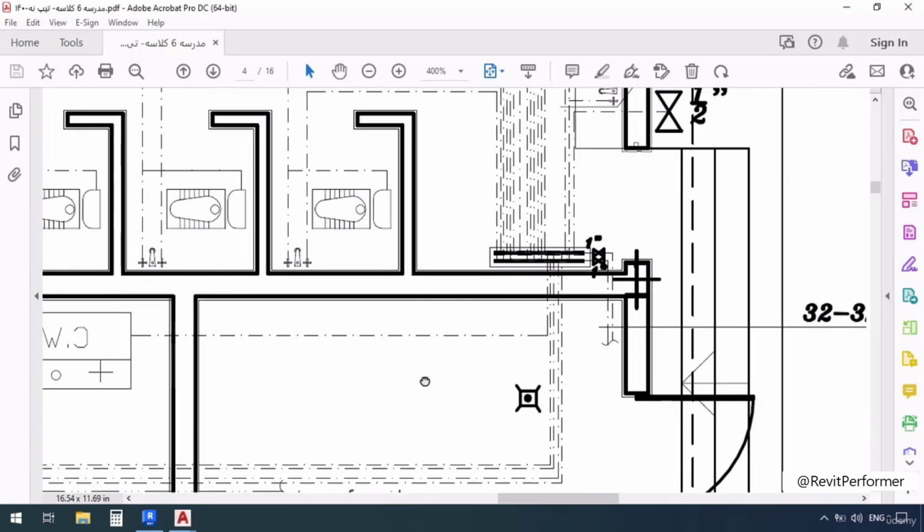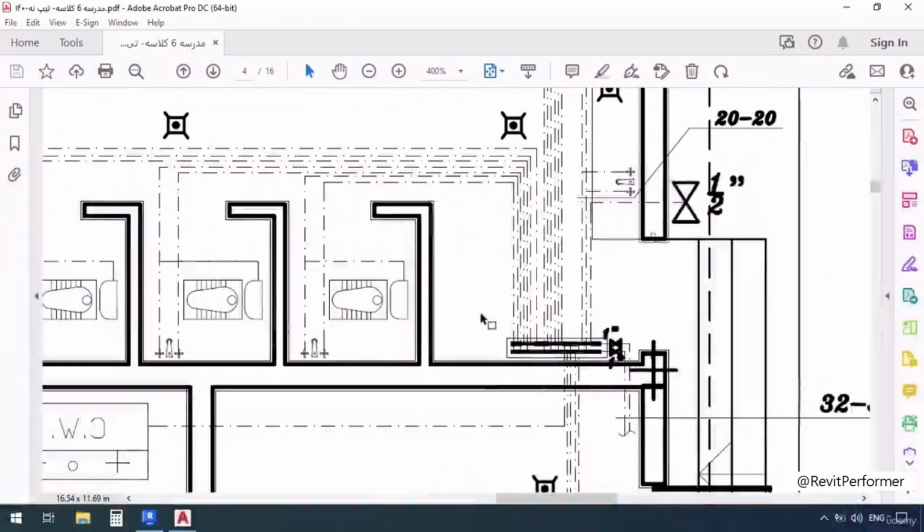Here in this area, we're going to be needing some domestic pipes to lead to the bathroom stalls. So what's going to happen? These 2 lines right here, the cold and hot water coming from the mechanical room, are going to go this way and end at this collector right here. And then we would have some outlets from this collector leading to the consumers.